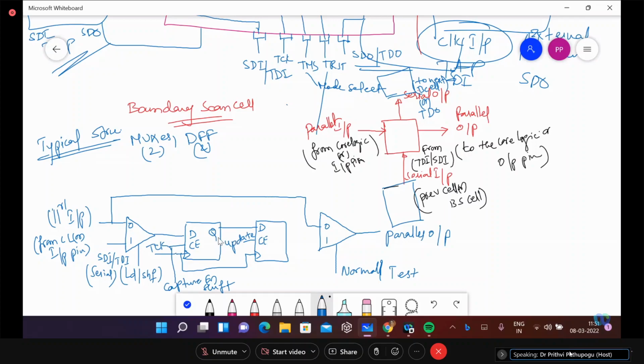So if you say first flip-flop and second flip-flop, this will be your input to the networks. Now, what are the things we were having: parallel in, parallel out we have given. And we need to take the serial operation. So serial operation is something like this is serial in and serial out will be here. This point is your test data output or the serial output point.